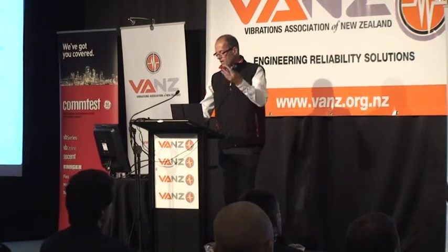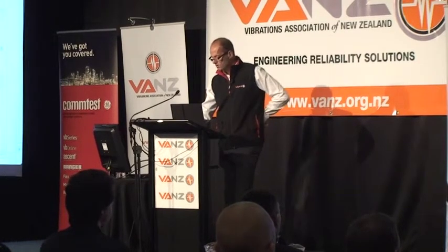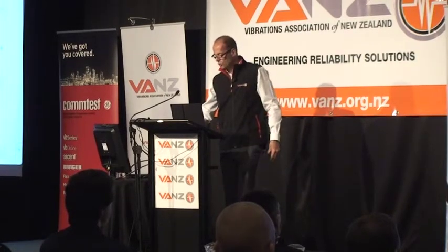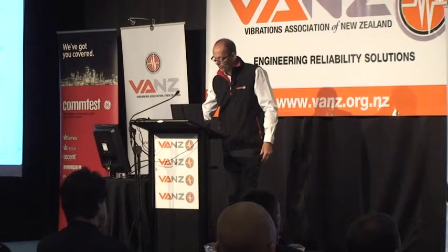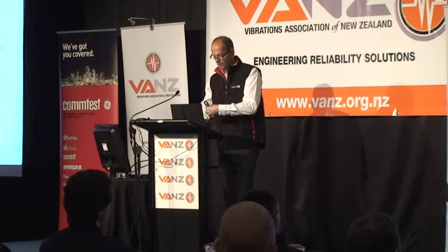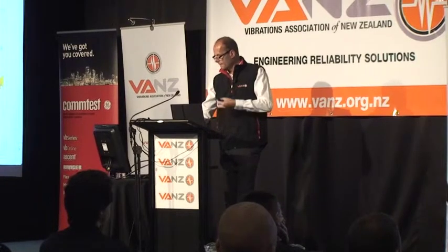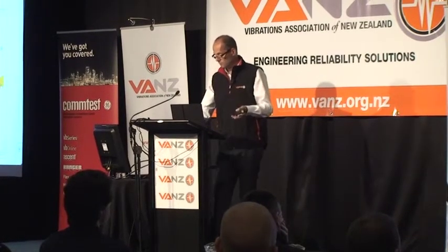And so here I'm showing it in sort of 3 dimensions, if you like. I've got the time, the passage of time as the machine's rotating, and the amplitude, but here I have frequency. So if I made it slower, all those little sine waves, they drop in frequency, but they drop along that frequency axis. But anyway, if I now look at it from this standpoint, that is when I'm actually seeing the spectrum. That is the spectrum.